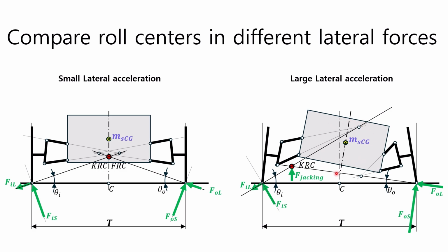If suspension roll occurs, the idealized spring model cannot be used because the forces acting on the links cannot be distinguished from the forces acting on the springs. For this reason, the roll center obtained in this way is neither a kinematic instant center nor a true roll center, since by definition of the roll center, the forces acting on the roll center should not cause suspension roll.